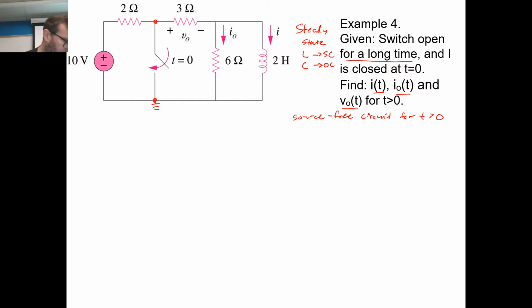Okay, so we can get the initial conditions, or ICs for short, from the no jump conditions. Remember that an inductor, just like a capacitor in our example on Tuesday, the voltage couldn't change abruptly. So from t equals 0 minus to t equals 0 plus, whatever the voltage was on that cap before the switching event occurred, it has to be the voltage on the cap after the switching event, because it's sluggish in responding to changes in voltage. It just can't do it abruptly. It has to take time, and so there's a continuity there. No discontinuity. There's no jumping.